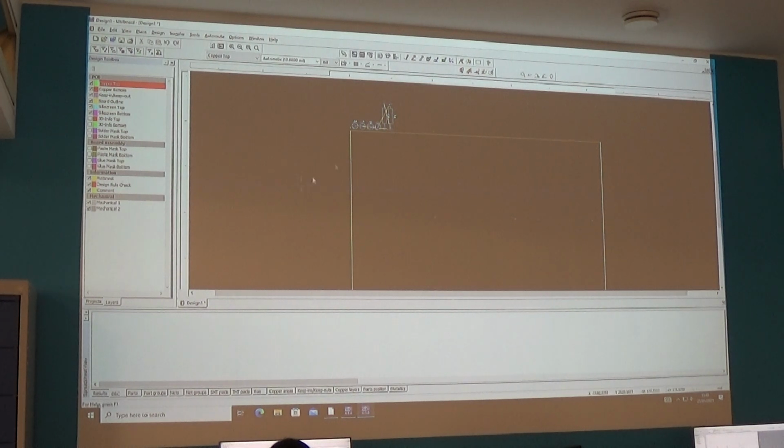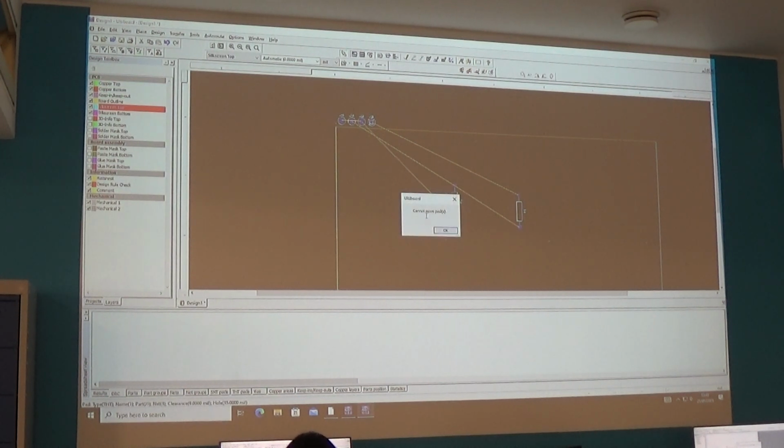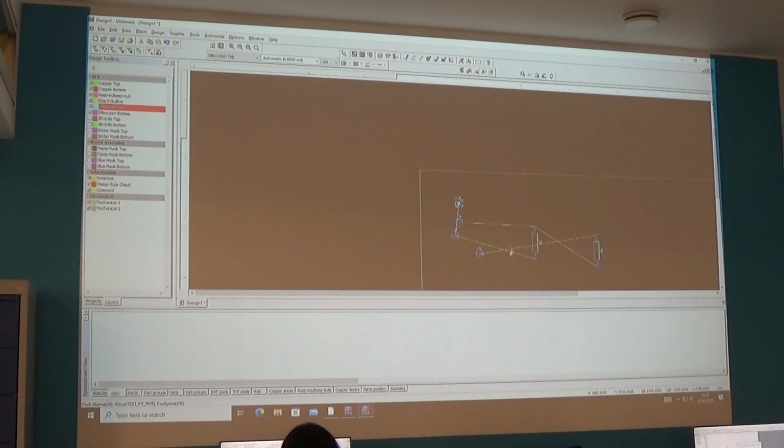So now I go through the process, and this a lot of people find tricky, but don't drag the pads. Drag these in, doesn't matter where, just drag them into the drawing area first, so you can decide. These pads are really difficult, you can't move pads, so sometimes you have to zoom in to get one. Drag those in, drag that into the drawing area, and lastly that one. Right, so zoom back out again.